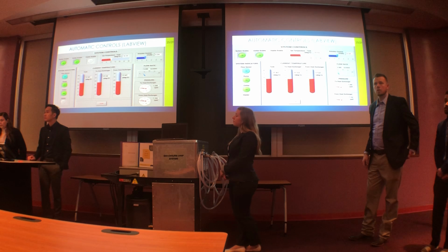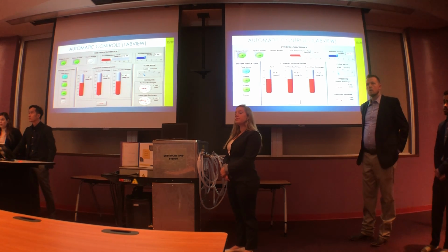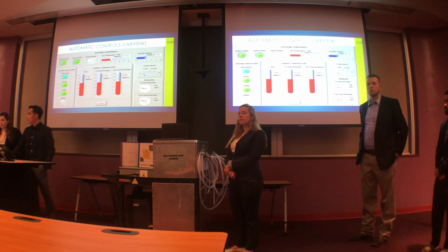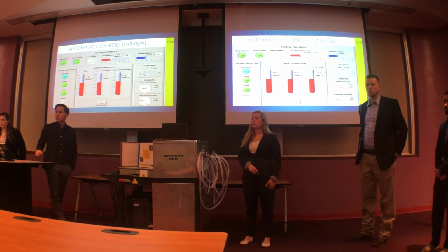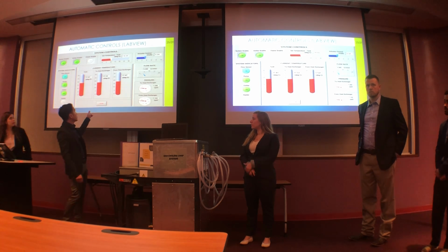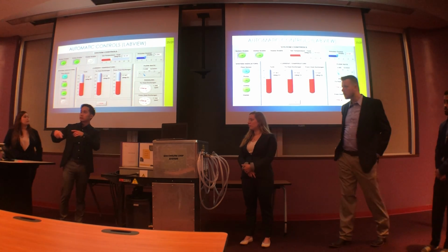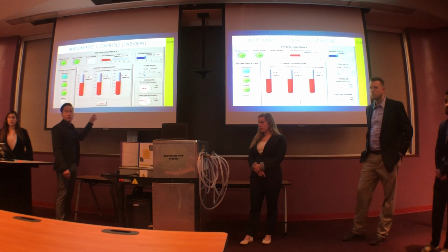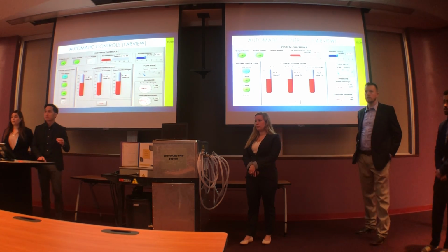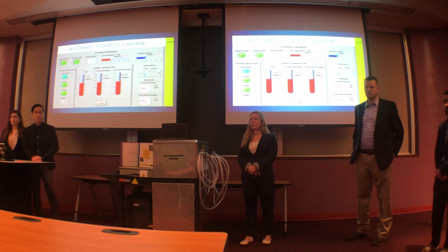Can you explain to me when or why the tank temperature would differ from the 2 heat exchanger temperature? Difference in thermocouple, just a variance. Right now we're not running to the supply, so it's a bypass. A three-way valve is in there.